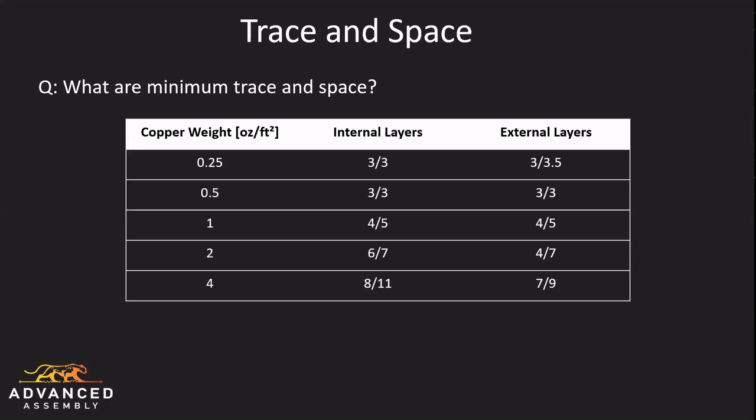Obviously there's nanotechnology and micro etching that you can do to ensure that extremely small conductor widths and extremely small spacing can be achieved. It's just, at the end of the day, going to be a conversation with your fab house on what they can do and certainly what they can't do. And they need to be honest too and say, look, this is something that's out of our wheelhouse. I don't want to give you expectations that we can and then ultimately fail.